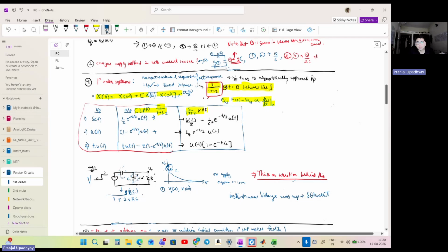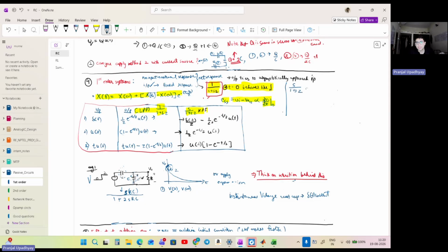Also, one more thing that I should mention is that as we said, a low pass filter at zero time will behave as a pure integrator. Similarly, this high pass filter also at t equals zero will behave like a differentiator. And I don't think it's anything to be surprised about. Again, we can take a simple example: we have this ramp input. In response to that, what we are getting is a slowly growing unit step function. If we observe it closely, we know that the derivative of this is a straight line only, right? And we can actually establish that near t equals zero, the behavior will be like that.